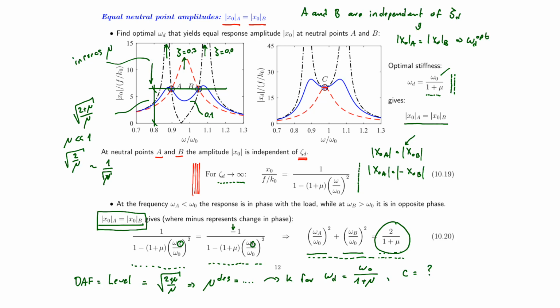And it has a slight overshoot just outside the omega A and omega B parameter frequencies, but inside it has a very small value. So thinking of the waterbed effect, one could argue that what if we could bring up this intermediate value? Could we then bring down these two outside resonant peaks and thereby get an even better and flatter curve?